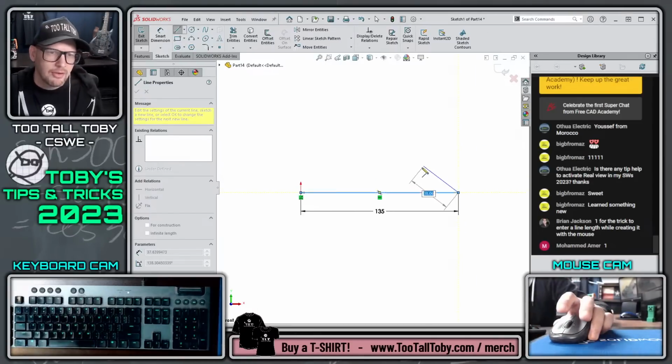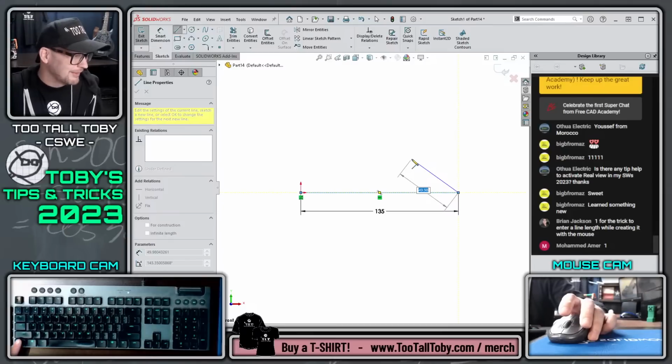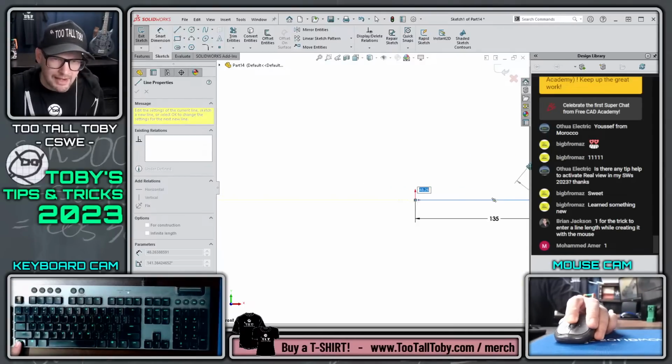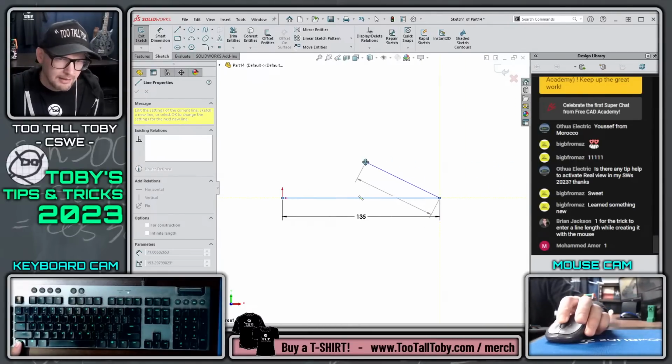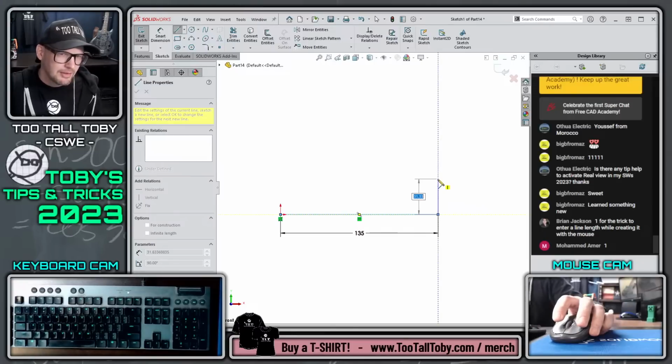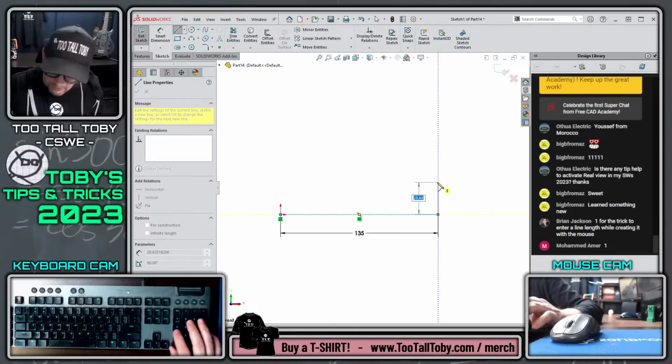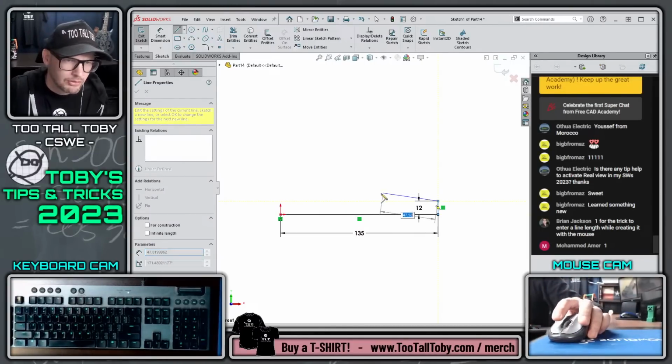And that was another little bonus, you guys get a lot of bonuses today. If you notice over here on this side of my keyboard, I'm holding the Control key, and if you look at my mouse, I'm pressing straight down on the wheel. That's the shortcut for pan. So you notice that my sketch is kind of off the screen and difficult to work with. Well, I hold Control and the middle mouse button and drag, and that's the shortcut for pan. And look, I'm still in the sketch line command, nothing changed. So a nice little shortcut there to keep moving through.